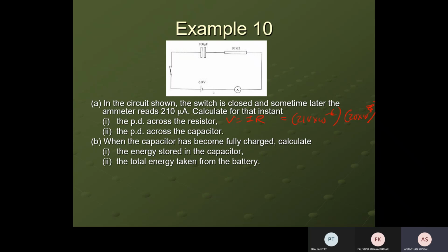Who shares the voltage of the battery? The capacitor and the resistor. As time runs, the capacitor voltage will rise and the resistor voltage will decrease to 0. After it is completely charged, the capacitor will have the same voltage as the battery.